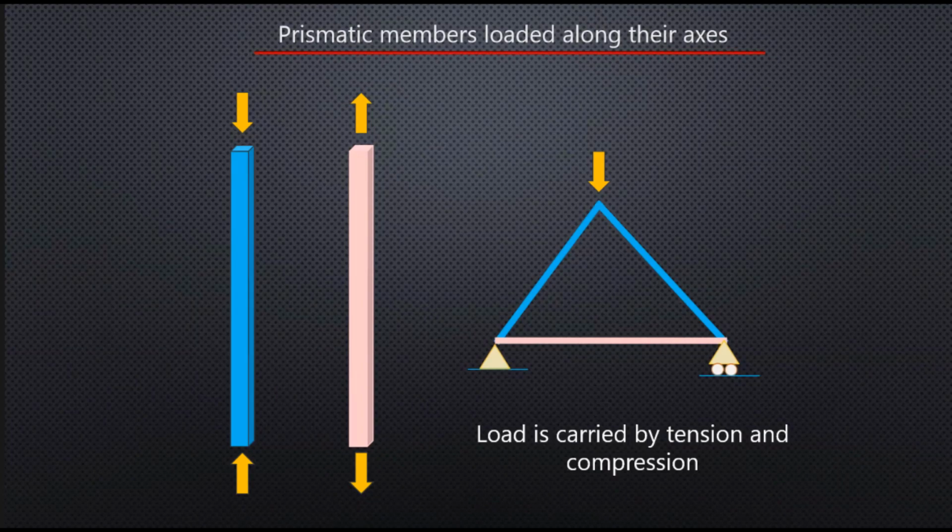Of course, I used to say the triangle is the most basic unit in any truss system. This system is geometrically unchangeable, and it is determinate. So if I can make the formations of the truss using these basic units, I can develop any number of different types of trusses.